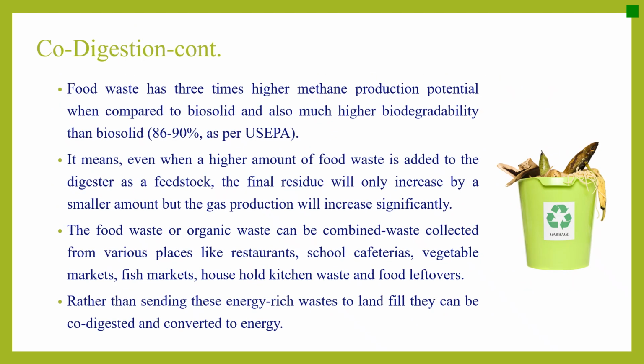Food waste is considered one of the high energy value co-digestion wastes because food waste has 3 times higher methane production potential when compared to biosolids and also much higher biodegradability than biosolids. It means even when a higher amount of food waste is added to the digester as a feedstock, the final residue will only increase by a smaller amount, but the gas production will increase significantly.